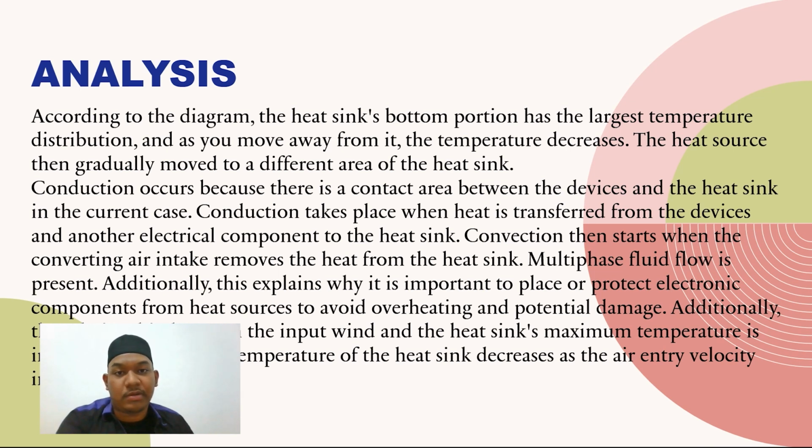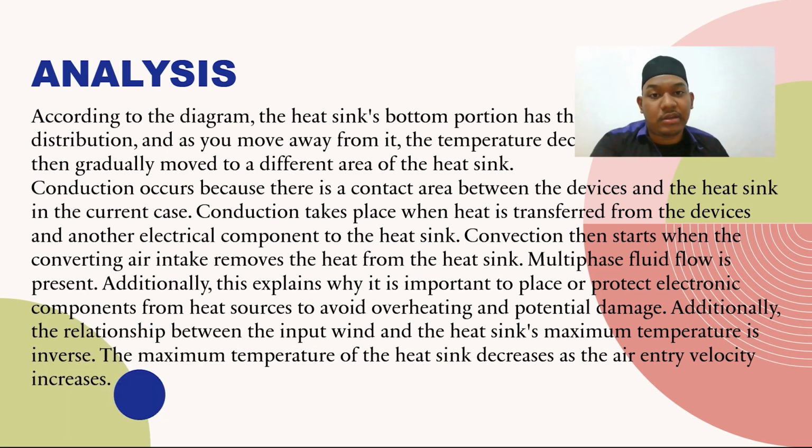Additionally, this explains why it is important to protect electronic components from heat sources to avoid overheating and potential damage. Additionally, the relationship between the input wind and the heat sink maximum temperature is inverse. The maximum temperature of the heat sink decreases as the air entry velocity increases.